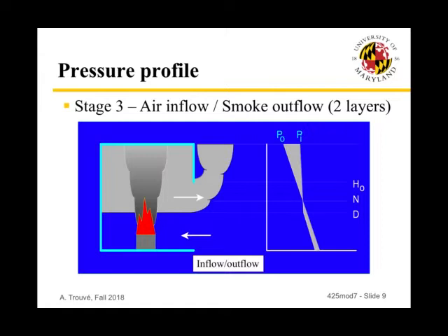So we can see that the smoke has descended further inside the fire room, but now because of the equilibration of pressure between the processes that drive pressure up inside the fire room and the vent flows that tend to decrease the pressure, we are reaching an equilibrium in the pressure changes between the variations inside the fire room and the variations outside. So we've reached a steady state.